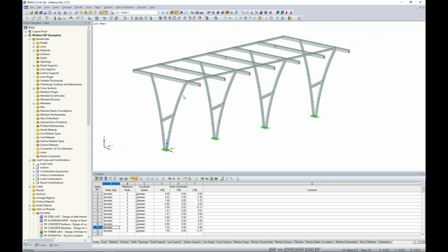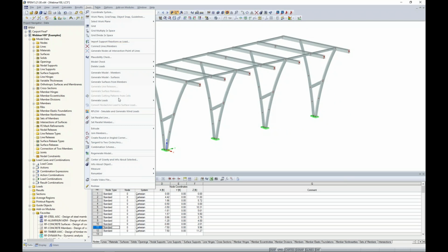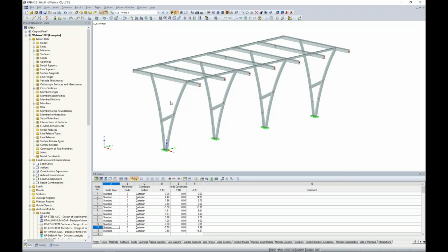Now, for wind loads, we do have an automatic wind and snow load generator. Now, the snow load generator would be efficient for this canopy type structure. The wind loads, unfortunately, cannot be used because we only have partially enclosed and enclosed structure for our wind load generator. Typically, for canopies, you would be considered as open structures, so we will need to manually apply our loads for today. So what we want to do is just to go back to the area loads on members via plane in order to apply those.